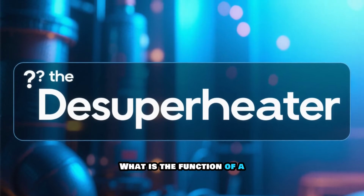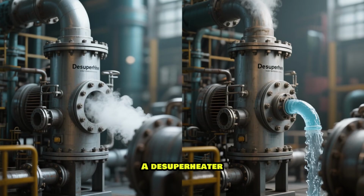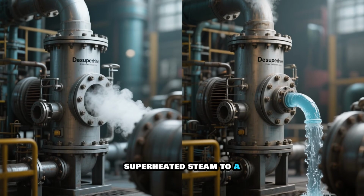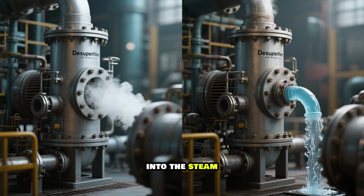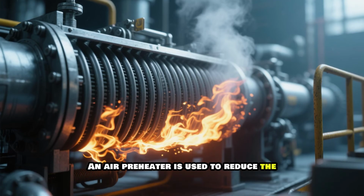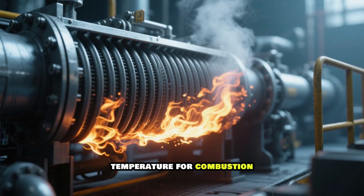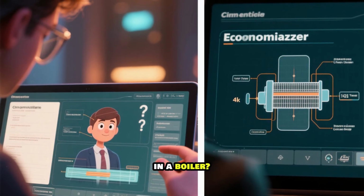What is the function of a desuperheater in a boiler? A desuperheater is a device used to reduce the temperature of the superheated steam to a desired level by injecting feed water into the steam. Why do we use an air preheater in a boiler? An air preheater is used to reduce the amount of fuel needed to heat the air to the required temperature for combustion.